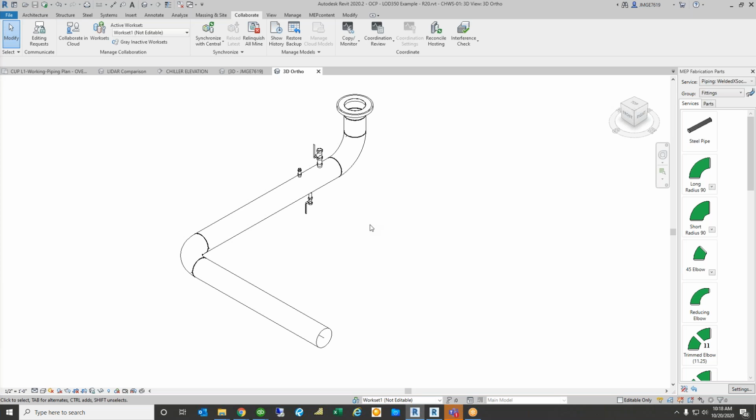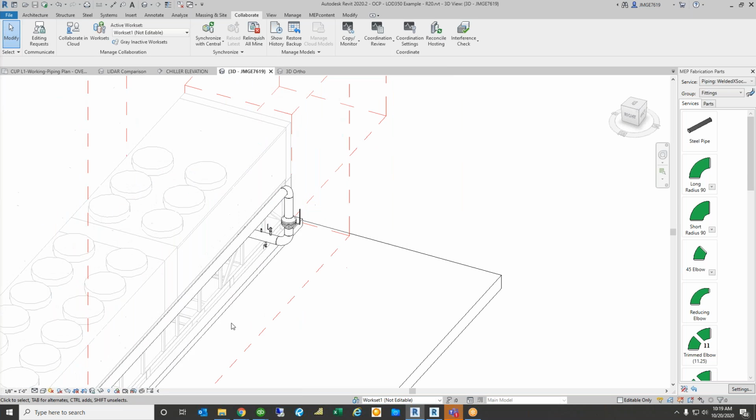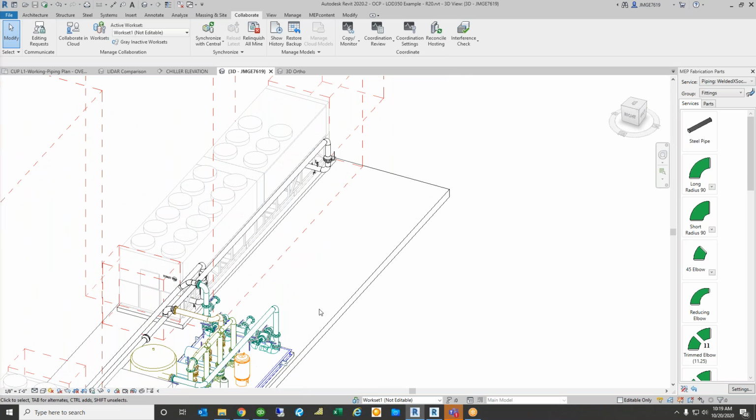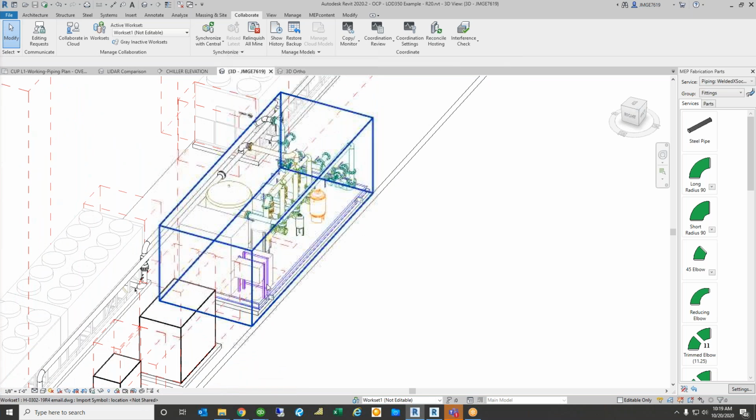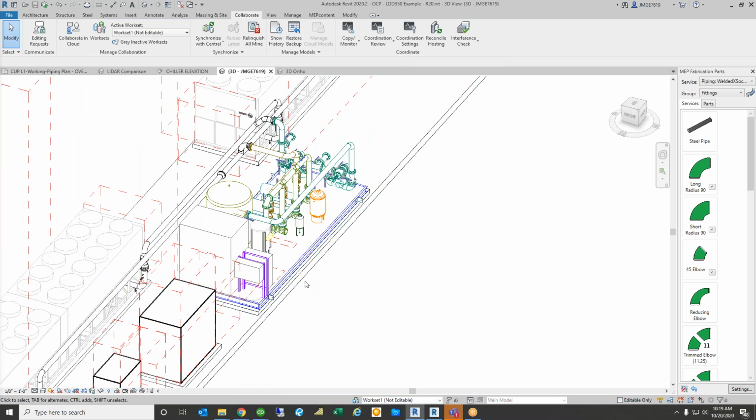And this really helps us move towards that discussion of being able to do offsite prefab, shop fabbing, shop examining welded pipe systems like this, recognizing, and this is a key part of the discussion, that riggers are good, and riggers can usually get this chiller and this pipe or pump skid assembly in almost the perfect spot, but there's going to be variations in the field, how the concrete's poured, how level it is, so on and so forth.